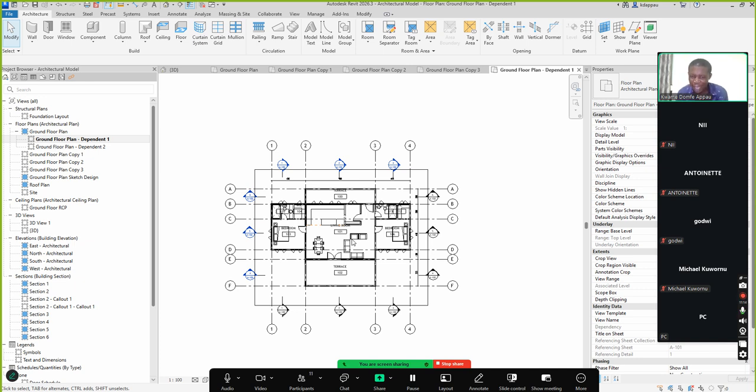That is why I took my time to go through how to create all these things. So from next week, any object that you take, we are going to edit the type properly, create right walls, create right columns, size our beams correctly, size our pipes correctly, do everything at least to level of development of 200. We call it LOD 200 level, so that the work will look nice in terms of presentation and form. Any question?